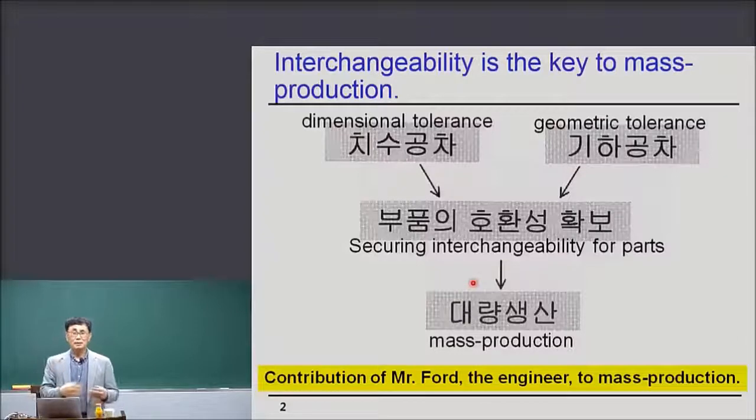Then, in the second step, you have to select the upper limit and lower limit, right? And the difference between the upper limit and lower limit is the allowable range, okay? So in step one, if you select a certain allowable range from the IT class, there are so many combinations of upper limit and lower limit, right?